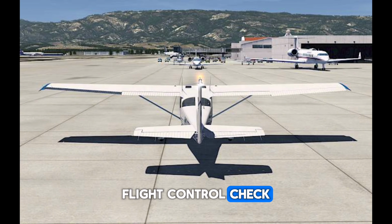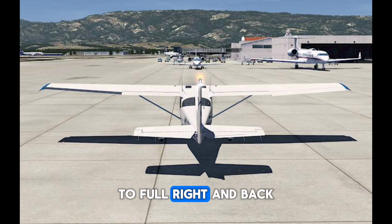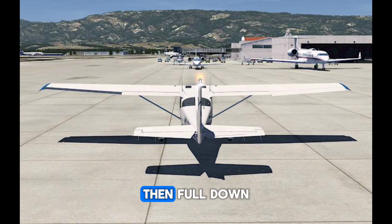Flight control check. Move the ailerons through their full range of travel, from full left to full right and back. Look at the wings and verify that when you rotate the yoke to the left, the left aileron is going up and the right one is going down. Verify that when you rotate the yoke to the right, the right aileron is going up and the left one is going down. Move the elevator full up, then full down.